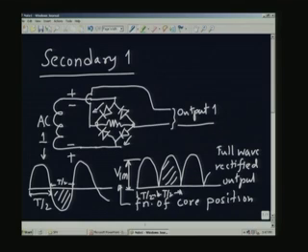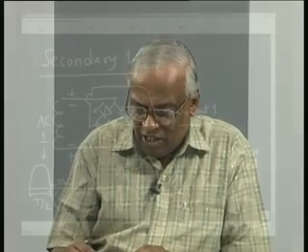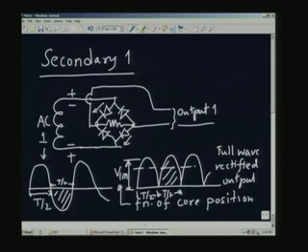So, if I pass this wave through a filter which is going to remove all the high frequency components, what you will get is only the mean value will come through, the mean will pass through. So, the average value will be something like this, or the V1 DC, V1 DC is going to pass through, the rest is going to be removed.